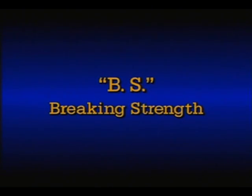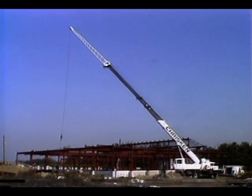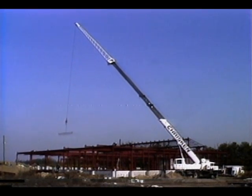BS stands for breaking strength. That's the load at which the rope breaks when new. FS stands for factor of safety. This is the ratio of breaking strength to safe working load. 3 standard formulas express the relationship between these 3 quantities.